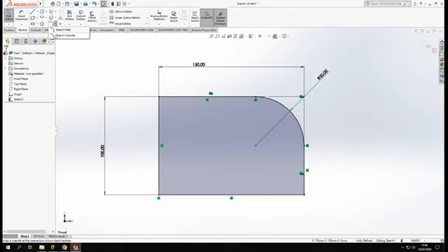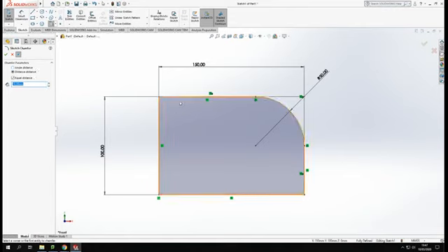And that tool is the chamfer tool. So looking at the chamfer tool, now when I'm chamfering here, I can chamfer an edge again, and I can do it by angle and distance. So if I click on that, angle and distance, I put in the distance I want to go and the angle I want it to be at, or I can do it by distance and distance. And if I've got it set as equal distance, I just need to type 1 in. And if I don't have that set, I can set the 2 different distances in there.